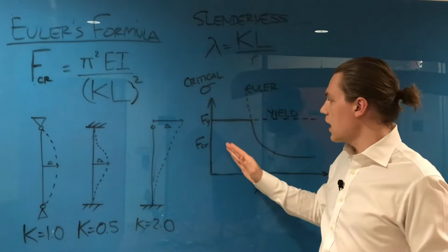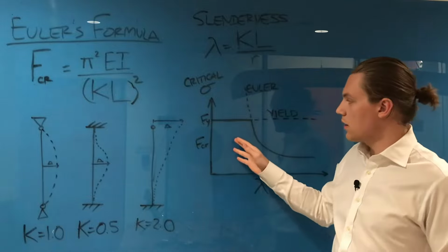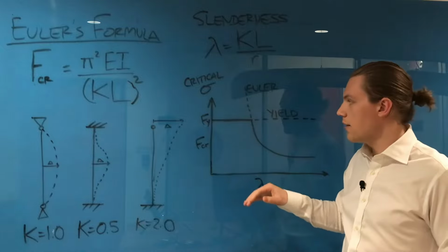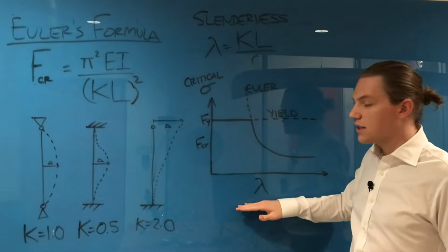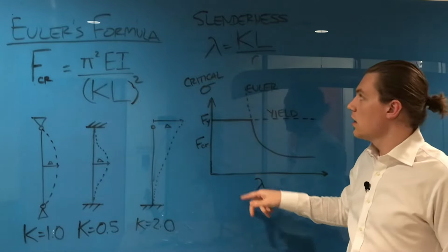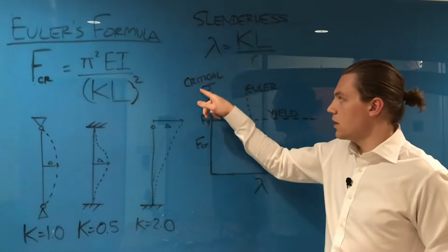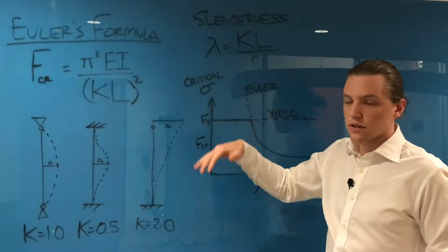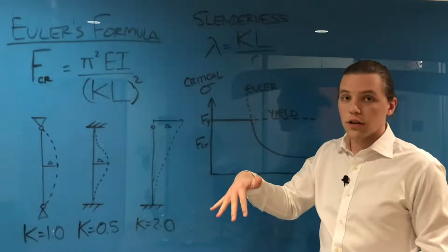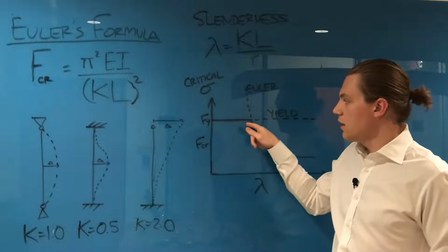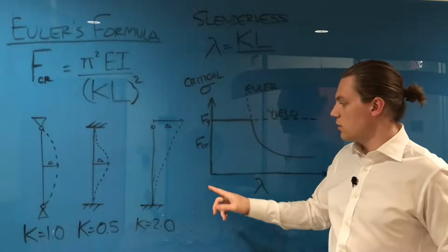And if we look at this graph here, now we're looking at the maximum compressive theoretical graph. So on the x-axis here we have slenderness ratio, and that's depicted up here. On the y-axis we have the critical stress for compressive or axial failure. And we have Fy here. This is our constant yielding stress. And actually what we'll do is we'll just start at 0.